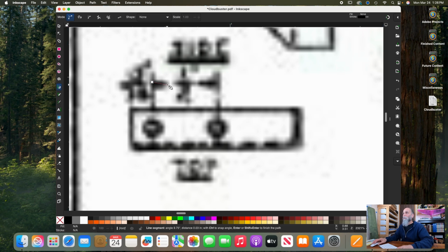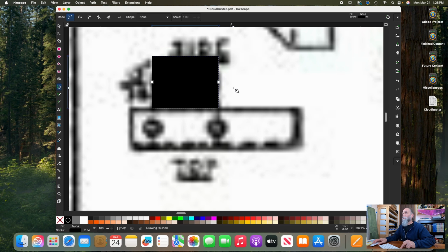So click it, and then if you hold the shift key down, nope, not the shift, the control key, see how it snaps to I think it's 10 degrees. So there is a perfectly vertical line, and there's a horizontal line. If I didn't do that, it would place it wherever I want, and I want to keep it horizontal. So it's the control key, it just makes it easier to measure, and I'll show you why here in a second. And I'm going to say it's right there, and it's a double click to break the line.